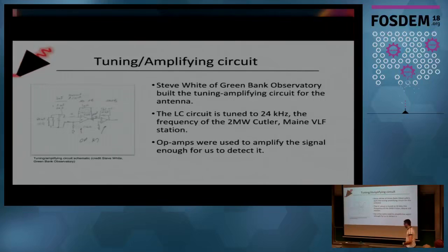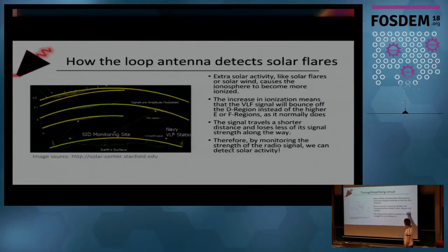And then you need some electronics, and that's where the fun starts, I guess. So this is an amplifier and some filtering, and a Ham It Up is then used to move the signal into a frequency range that is receivable by the RTL-SDR. So why do you need the Ham It Up? Because the idea is to track VLF signals.